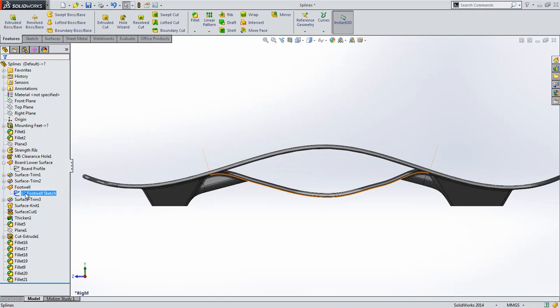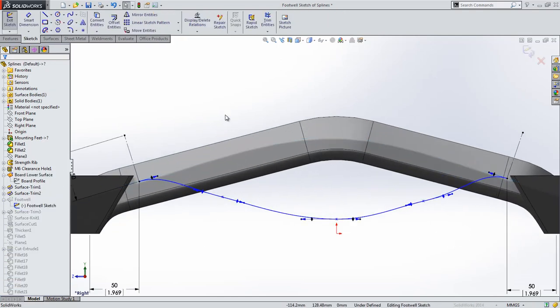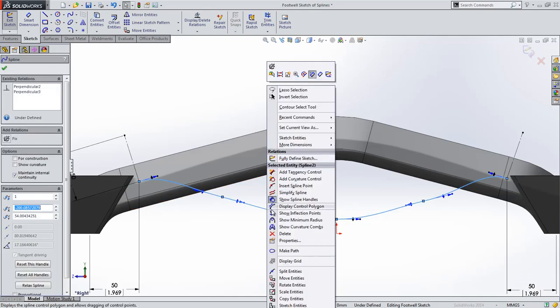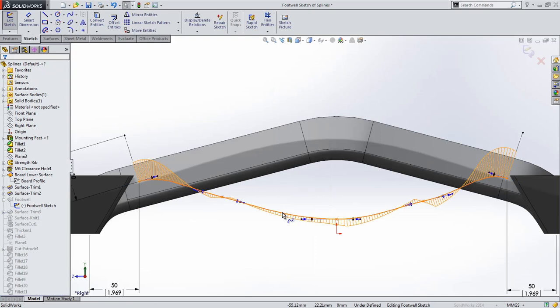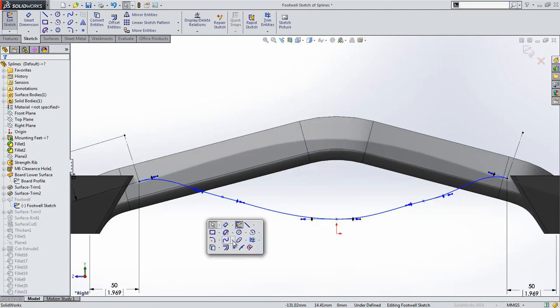Finally, while we're talking about splines, sometimes, especially for new users, they can be intimidating trying to get all the geometry just right. Controlling the inflection and maintaining a smooth profile require proper definition of spline points, such as this spline here. SolidWorks 2014 introduces a completely new spline tool that removes all of these concerns, called the Style Spline.